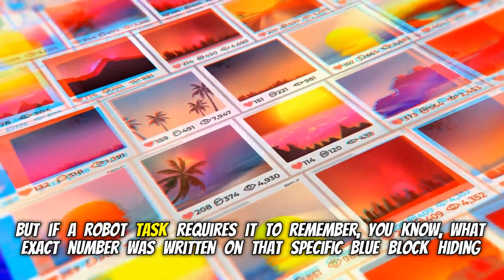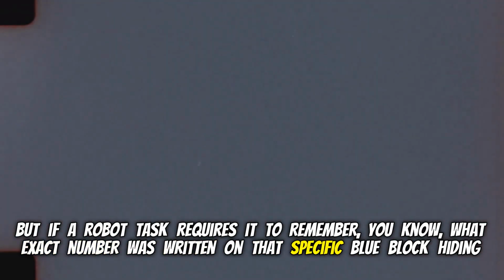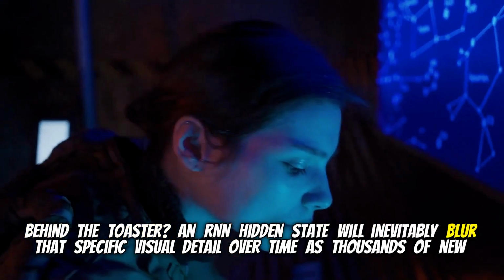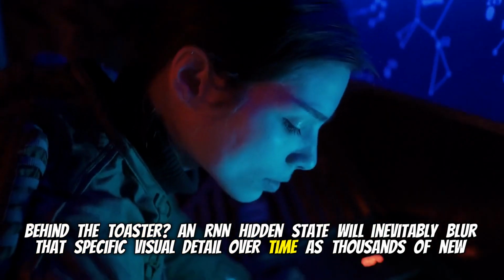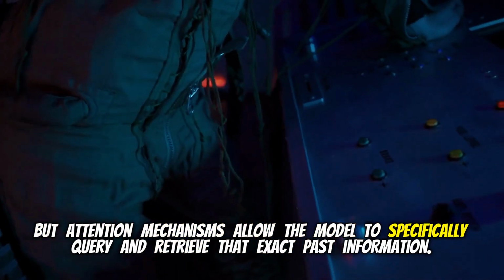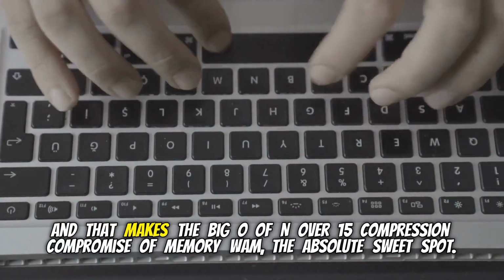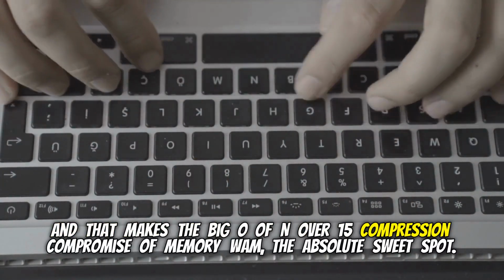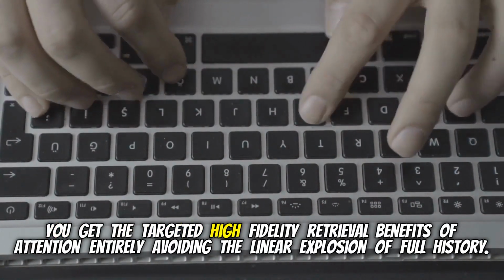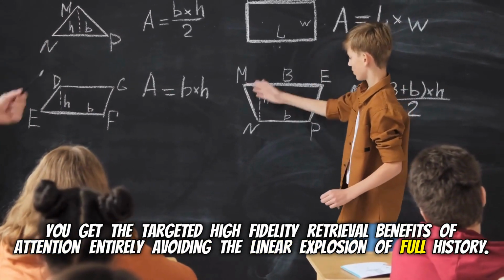But if a robot task requires it to remember what exact number was written on that specific blue block hiding behind the toaster, an RNN hidden state will inevitably blur that specific visual detail over time as thousands of new frames overwrite it. But attention mechanisms allow the model to specifically query and retrieve that exact past information. Exactly. And that makes the big O of N over 15 compression compromise of MemoryWAM the absolute sweet spot. You get the targeted, high-fidelity retrieval benefits of attention, entirely avoiding the linear explosion of full history.